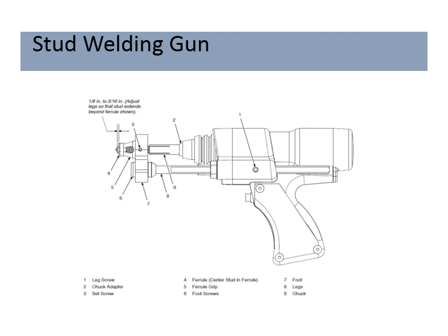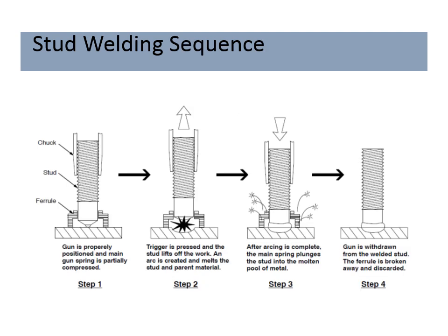And you're going to have this stud, basically a nail, an attachment that is welded. It's fused onto the base material. A lot of times it's like a steel girder or an I-beam that you're going to use to pour concrete on. It'll be some kind of deck, like a floor. So this is what a stud weld gun looks like.